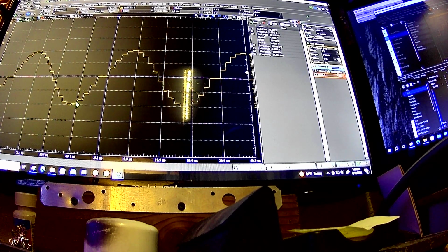They're still quite jaggy, but again, that can be filtered out with the same exact filter I was talking about before, because it's still all got the same slew rate. And it's this slew rate that's responsible for generating those harmonics. It's really this transition from one level to another that's doing it, and the larger that transition, the higher the amplitude of those harmonics.